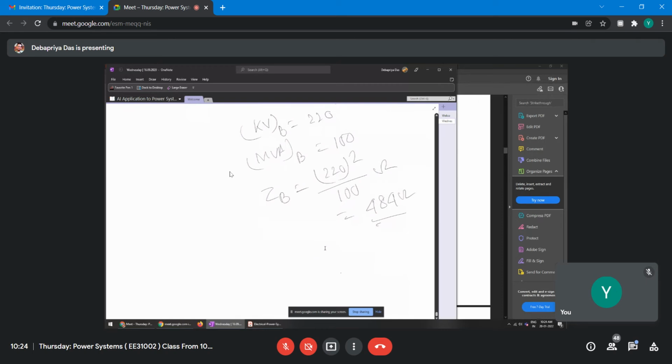In your first year, from the middle of the second semester, the lockdown started. So whatever you have studied regarding power, whatever we do in electrical engineering, because I have not taught you power system. For example, whenever we write the power equation, generally we follow P minus JQ is equal to V conjugate I. Or if you take the conjugate on both sides, P plus JQ will be V I conjugate, right? Now, why does this conjugate come? Just to capture the power factor angle.